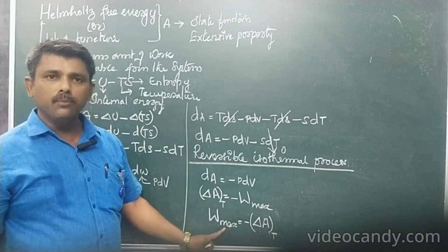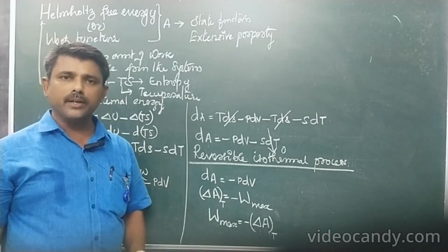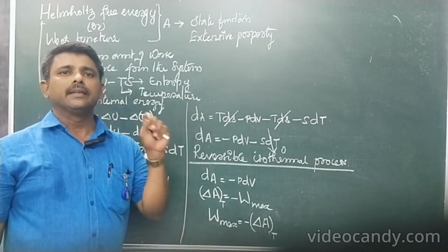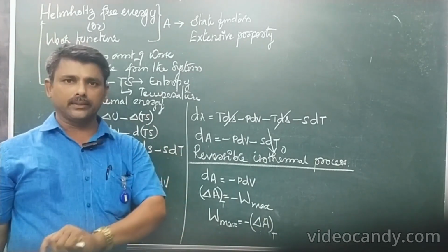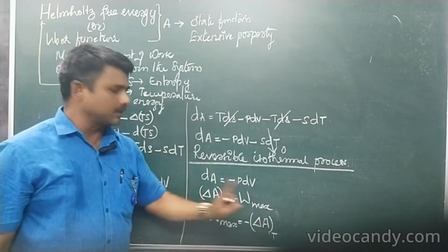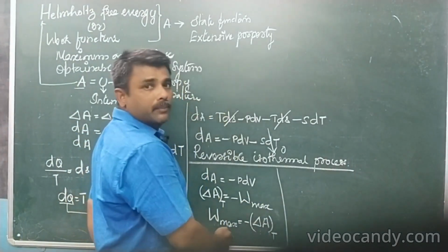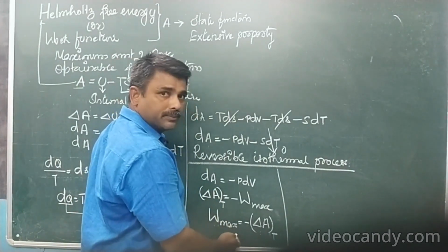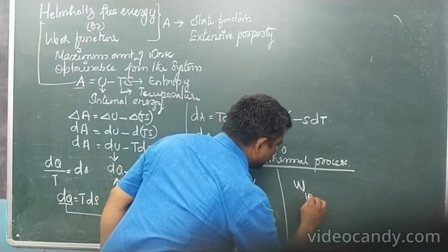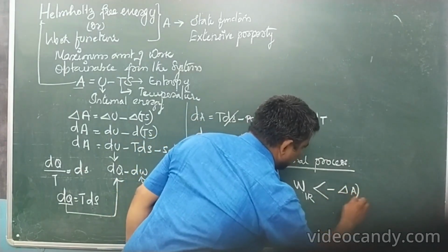So knowledge of Helmholtz free energy is very much important in thermodynamics. It is useful to find out the maximum amount of energy that can be converted into work, or the maximum amount of work that can be obtained from the system at constant temperature. If it is an irreversible process, W irreversible is less than the decrease in Helmholtz free energy.